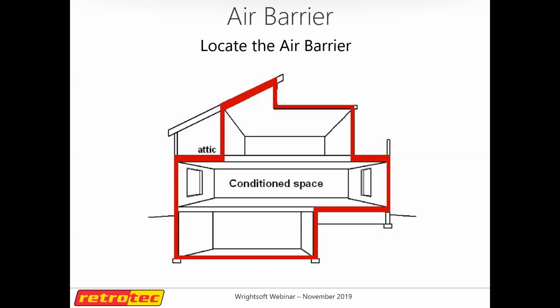In northern climates, you get a lot of basements that aren't insulated and don't have any supply runs. What they do have is a bare metal leaky duct system in the basement. You get into that really weird turf of, am I intentionally conditioning this, or is it just happening by accident? It's not a subject I want to dive too deep into here. But sure, that's where it gets a little weird. Unintentionally conditioned. Yeah, I hate it. It's such a bad idea. Seal that duct system, put a supply register in it for goodness sakes.